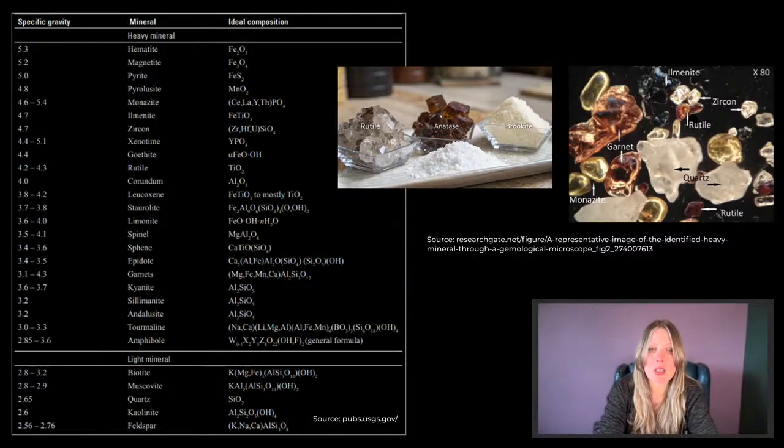The only exception is in rare drill holes where very high grades compensate for a thickness of less than 2 meters. Once the roof and the floor of the ore layer are outlined in each drill hole, the next step is to delineate the calculation block in plan view.